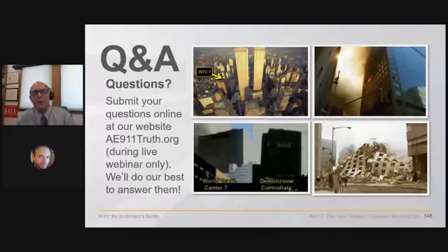No, this is what controlled demolitions do. They impose 45-degree cuts on structural steel columns and then use a kicker charge to kick the top one off the bottom one so that it falls without banging on it. They do that on all the columns at once, so the building can fall at or near free fall acceleration. And then the impacting energy of the building is used to further destroy remaining structure that wasn't destroyed by explosives.